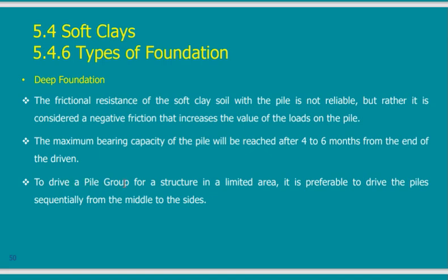To drive a pile group for a structure in a limited area, it is preferable to drive the piles sequentially. Yes, this is something related to pushing the water. When you push your pile inside the soil, it pushes water. So imagine that you started by doing piles all around your site.